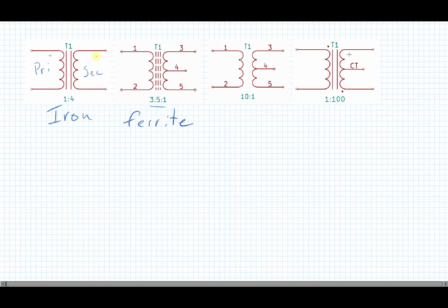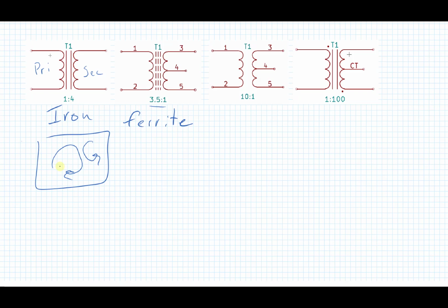Ferrite. Basically that's a ceramic material that has iron powder in it. The idea is that in an iron core, eddy currents would just flow around randomly. Basically current is flowing in that iron, drawing power and creating heat in the core, which is not doing us any good.